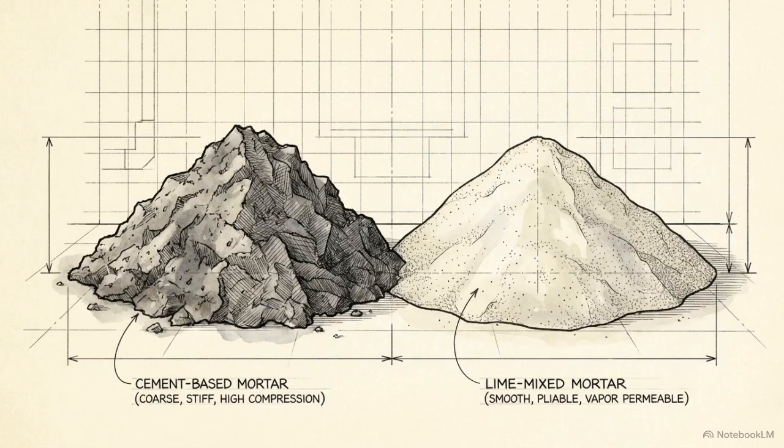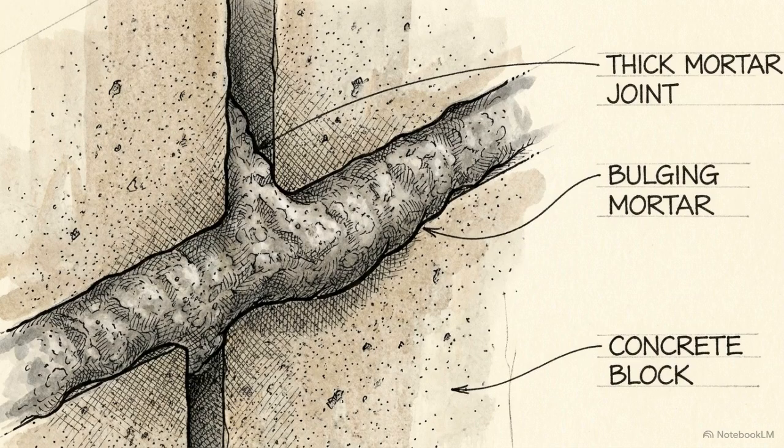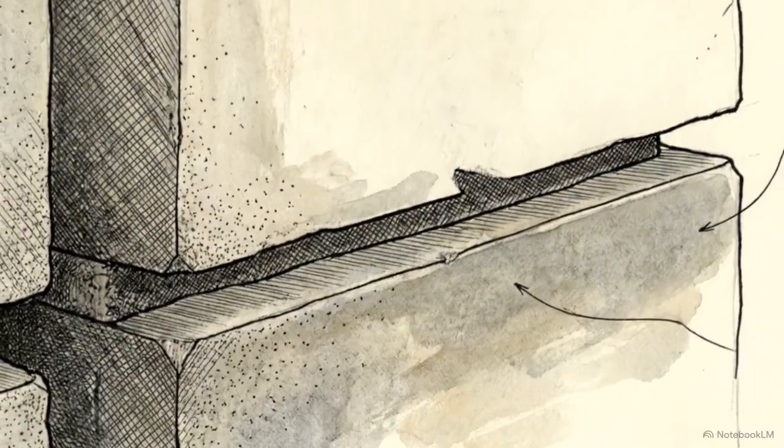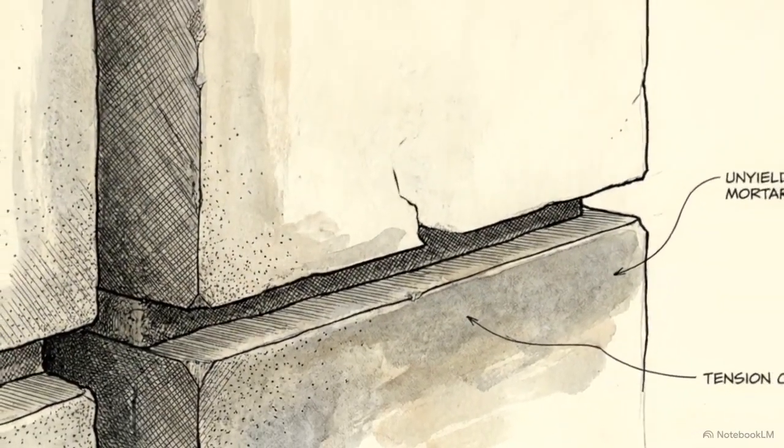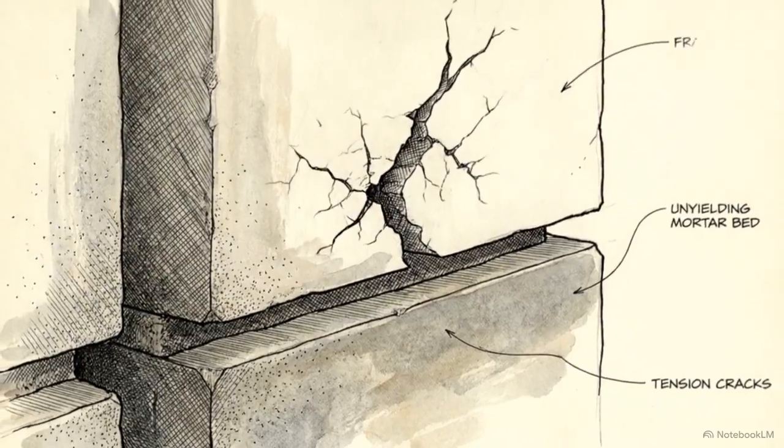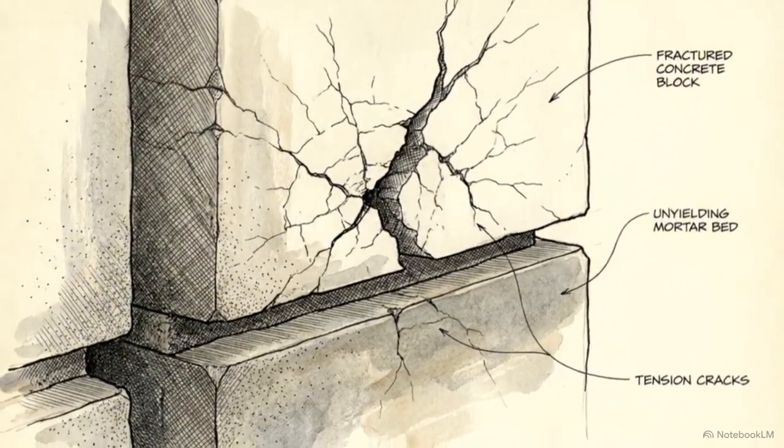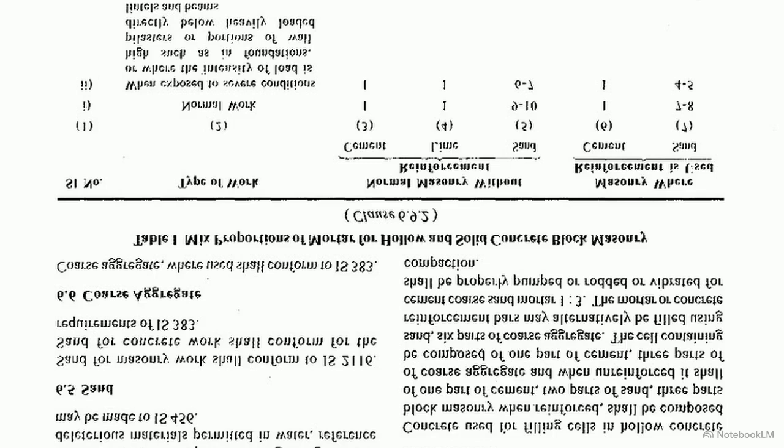Using a stronger mortar mix often creates a weaker wall system. A highly rigid mortar acts as an unyielding constraint. When the blocks undergo minor temperature or moisture expansions, the rigid mortar forces that stress into the units, causing structural fractures. IS 2572 mandates an engineered solution using composite mortar mixes designed to remain relatively weaker than the blocks. Adding precise proportions of hydrated lime to cement and sand increases plasticity. This creates a yielding buffer that safely absorbs micro-movements across the wall.